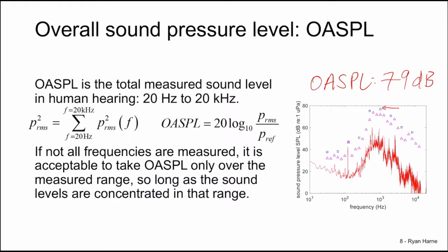It is important to recognize that the sound quantities we're dealing with are logarithmically presented in the decibel scale. So that means the values that are highest are many times greater than the ones that are lowest. So for instance, the values around 40 decibels are 2 orders of magnitude less than the highest values presented here in terms of acoustic pressure amplitude. So very often we anticipate that the OASPL value will be dominated by the highest of the octave band values.